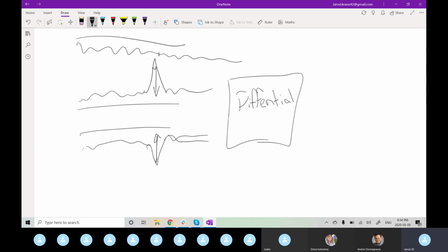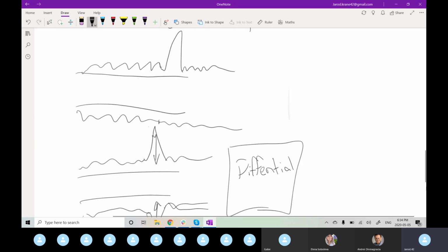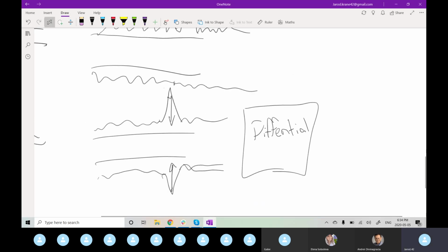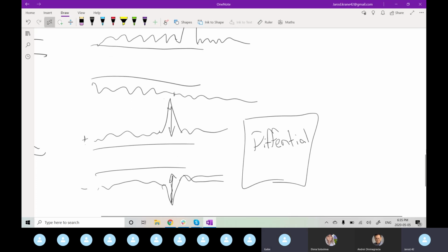It'll detect the two peaks and cancel them out, because you're sending one as a positive signal and the other as a negative half. When you take the differential, you're basically able to cancel out any obstructions, poor signals, noise spikes, interference. Gabe can talk better on this.